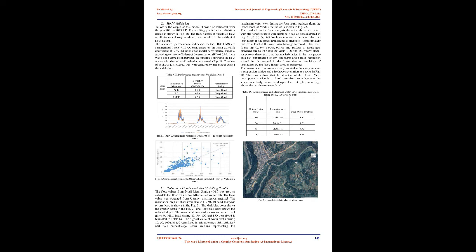Cross-section cut lines. Section cut lines with green cross marks drawn perpendicular to the flow direction were used to extract altitude data to create a surface profile throughout the channel flow. In addition, it must cross the center line of the channel, bank paths, and flow path lines as in Fig 13. These flood values and the appropriate boundary conditions were used as input for steady flow data.